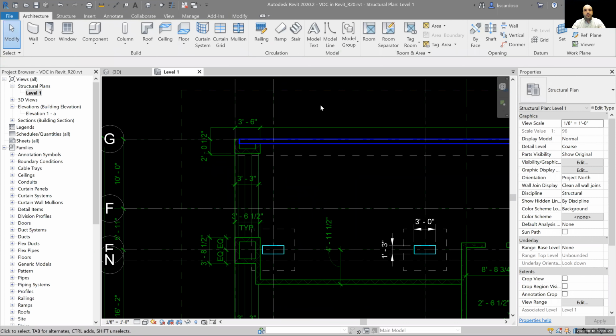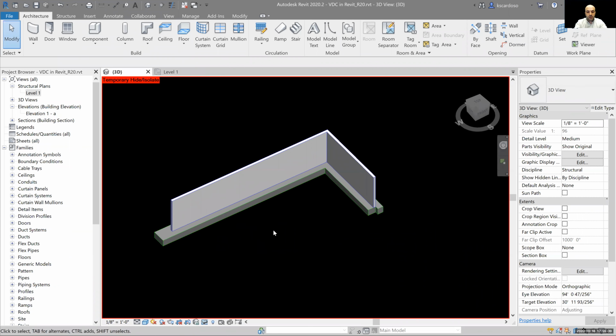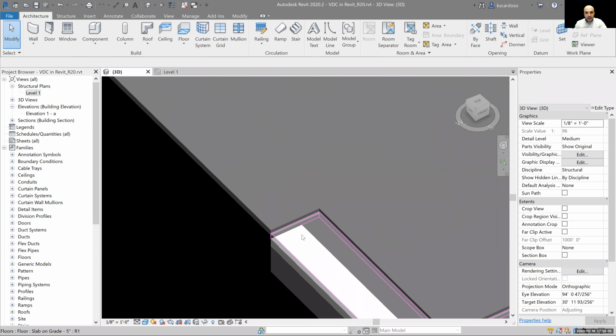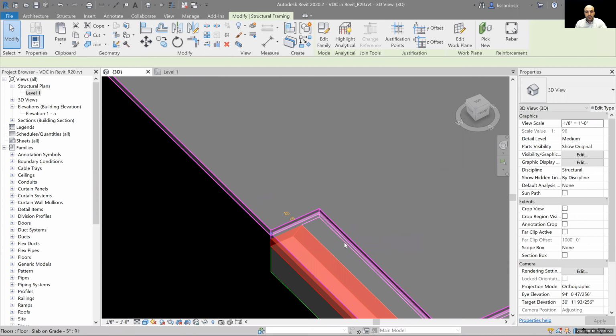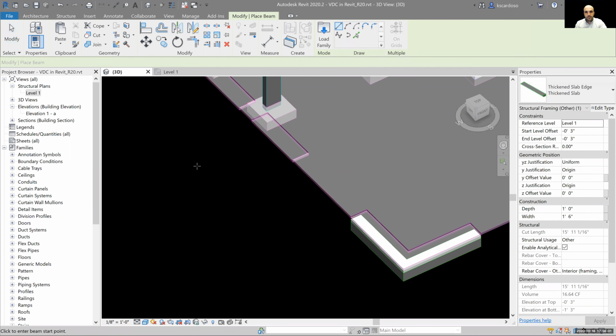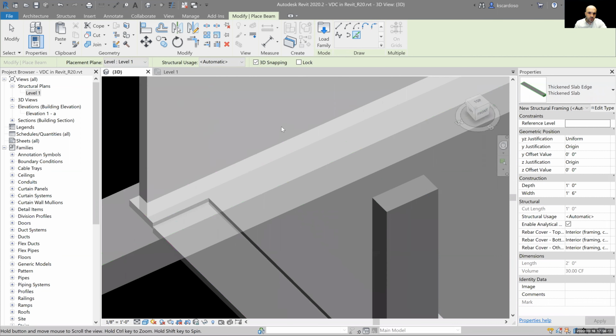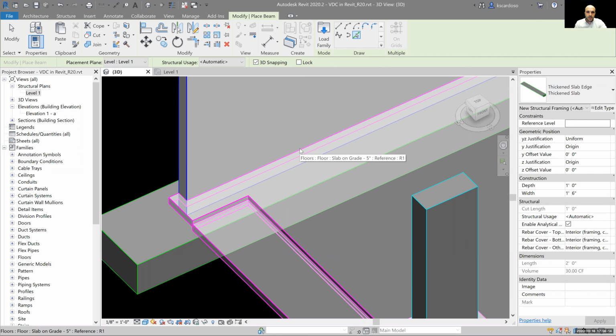Okay, so where does the thickening fall into place now? Well, this is the difference in the workflows. So if I go into my 3D view and I restore my view here, HR, right here, my thickening is just a filler. And it helps with 2D representation, right? If you were to cut a section there. So this is where I can go ahead and add a thickening. If you have a thickening in your project, just go ahead and look for one. And then on your keyboard, type in CS for create similar. My 3D snapping tool should default to be on because that was the last setting we used. And I'll hit pick lines and I'll hover over that inside top edge of the floor and I'll click to place.